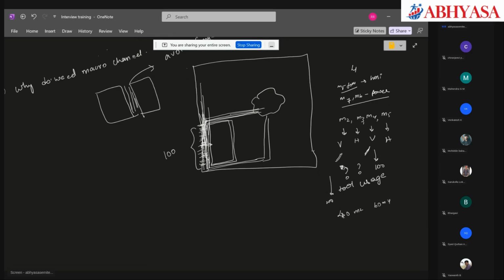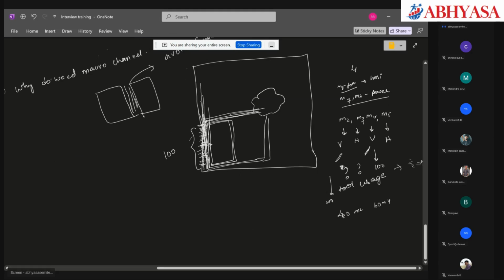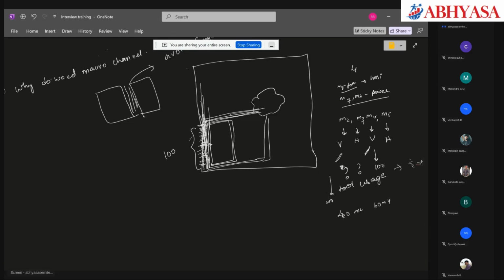Can we guide that? Yes, we can guide the tool and say for these net names use M4, and for the rest your choice. Or we can say for each of these 100 nets use this layer. But it is a very tedious process, right? We cannot guide every net in the design. Otherwise, what is the point of routing? We can only manually route. The tool has to choose appropriate layers for the design, right?